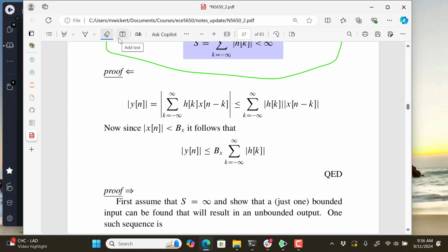But if I put in a particular type of signal that would be positive and then negative, where the impulse response is negative, then I would add and I would get that greater value. So it's being pessimistic. It's taking into account the fact that a signal might hit this at a resonant point and get a greater output rather than averaging to 0. And that's because you see the absolute value in there.